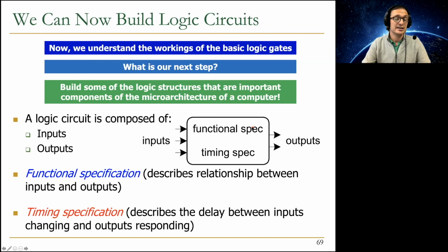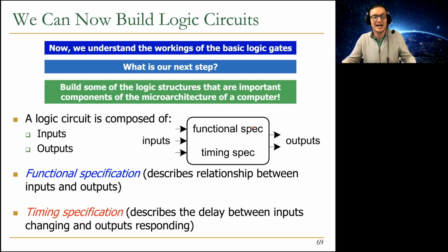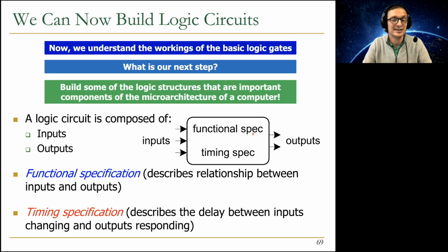And then I can use Boolean algebra, and then I can convert it into NAND gates, for example, or NOR gates, or AND or NOT gates, or whatever gates I have in my library collection, right? So I can start with a truth table, basically, and that's a great way to start, actually, to build logic circuits. You have this function that you want to implement. You know what truth table implements it. You start with a truth table, and then you basically compose that truth table into NAND and NOR gates. And we're going to talk about how to do that in the rest of this lecture, plus the next lecture, let's say.